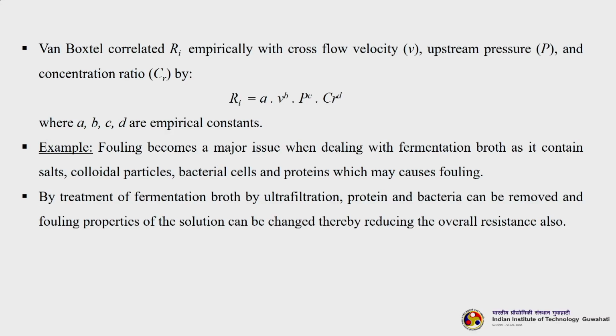So, fouling becomes a major issue when we are dealing with a fermentation broth, as it contains salts, colloidal particles, bacterial cells, and proteins which may cause fouling. Most of them are biofoulants. So, by treatment of fermentation broth by ultrafiltration, protein and bacteria can be removed and the fouling properties of the solution can be changed, thereby reducing the overall resistance also. Then again it can be sent to the nanofiltration system.